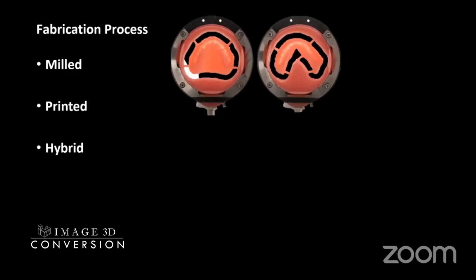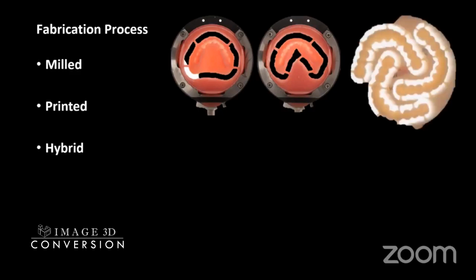You can see this is a milled denture base. The discs are available, acrylic discs, pink color discs. So we design them in the CAD software and the milling process goes on. Similarly, the teeth are milled separately. The teeth and the pink and the white have to be done separately. And these teeth are milled in PMMA blanks, again with the different shades coming in from A1 to A2, A3.